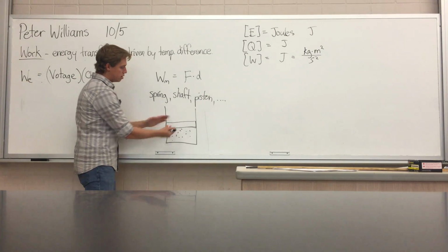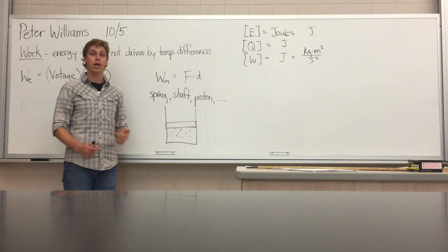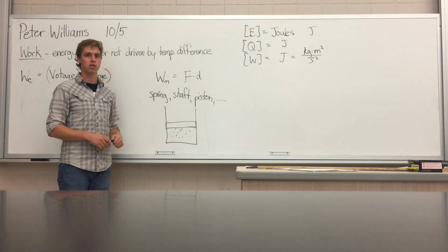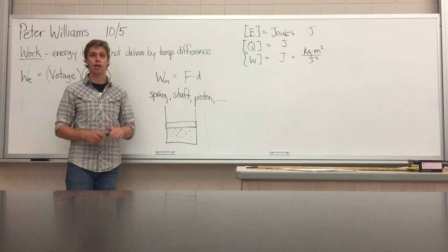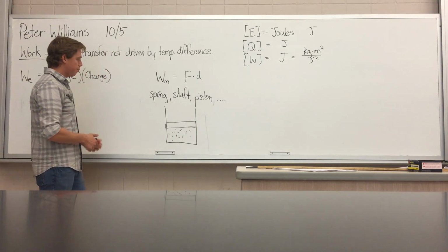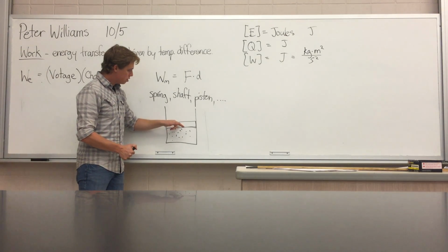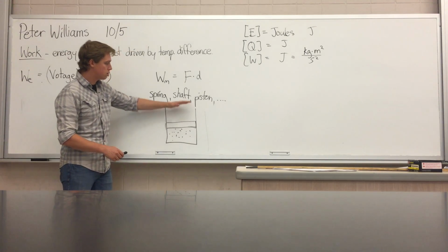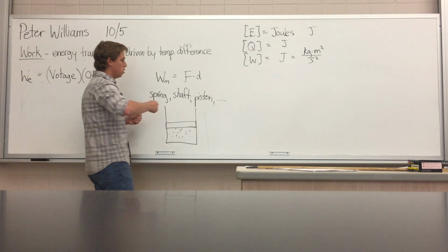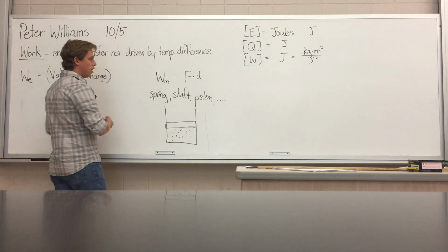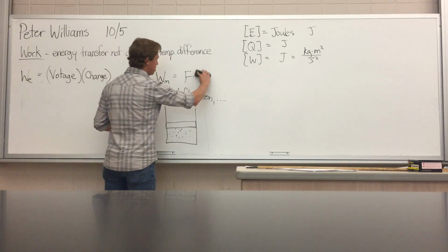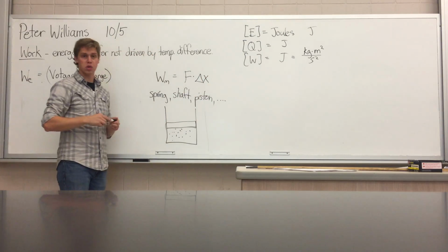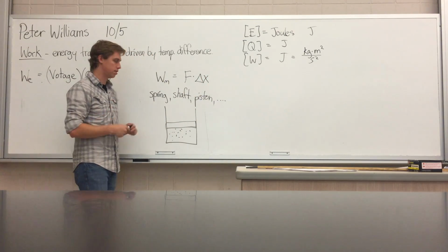We know that when it expands, it's gonna push this piston up. So it's doing work. This actual gas itself is doing work. And that's what we're gonna derive the formula for, because that's the main thing that we care about for today. So when this piston is pushed by this gas, it moves through a specific distance. So let me be a little more exact and call this delta x for the change of position, right? Force times a delta x, that's the fancy way of saying distance.